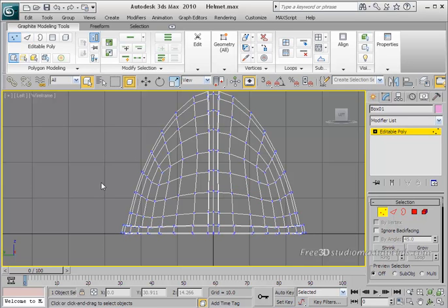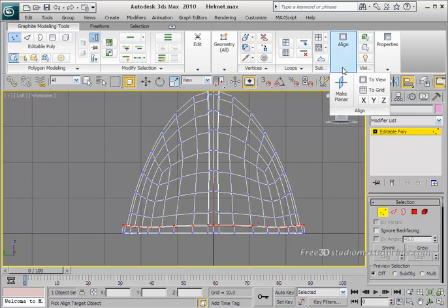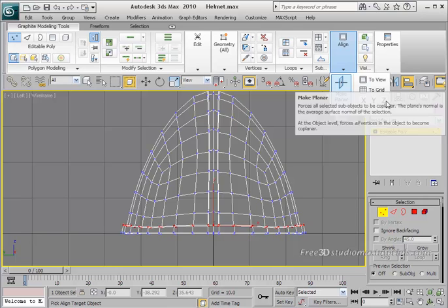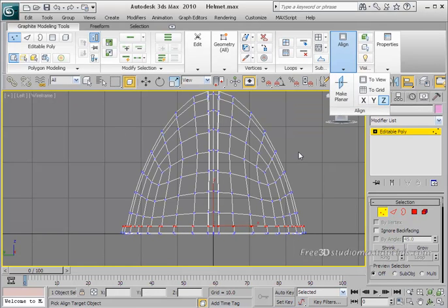Okay, just click in the screen to deselect the selected vertices, and with the region selection, just select this line very slightly. Okay. On the align panel, click Z to align all the vertices along their average orientation on the Z axis. Simply just click on this align button, and in the drop down list, click on the Z.